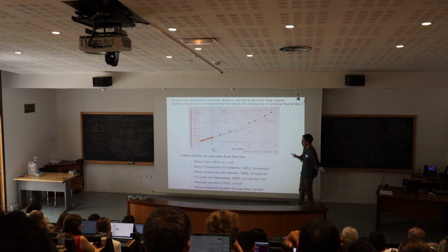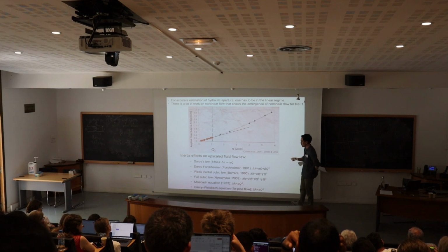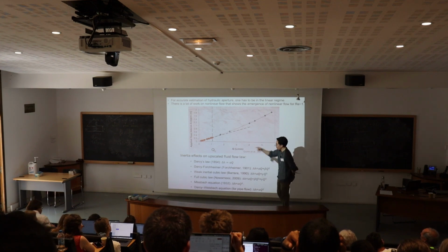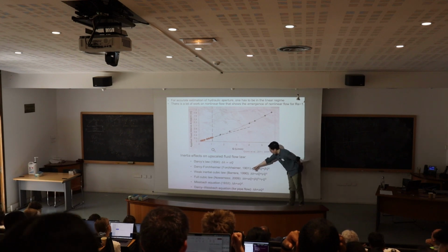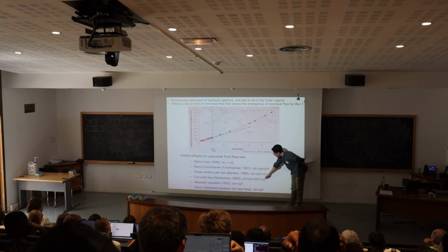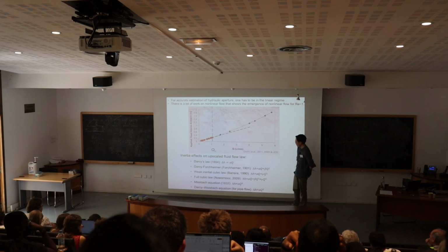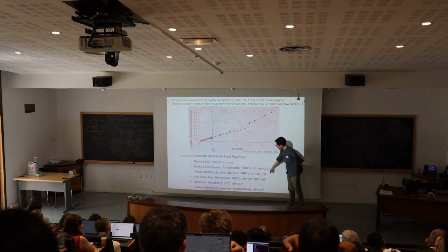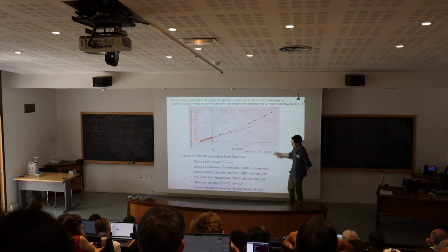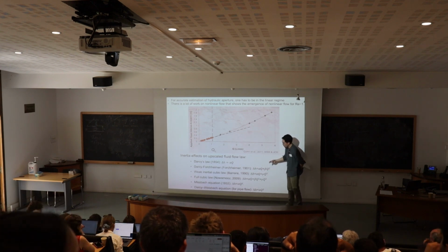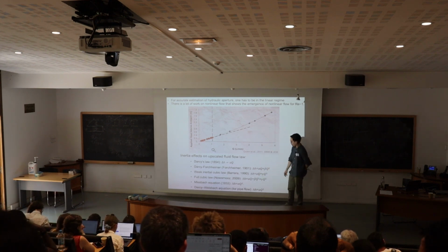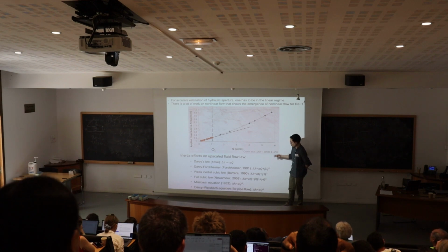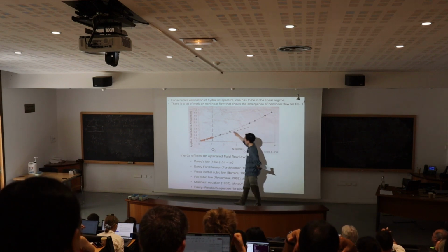And what's interesting is there's another cubic law. So you have to be careful when fracture hydrogeologists say cubic law, it's mostly the other cubic law that we derived. But actually there's another cubic law which is relating again the head gradient to the Q. And it's called cubic law because there is a third order term here. Okay? And I don't want to get into detail again, but some people argue that in the weak inertia regime where the flow is not turbulent, it has to be power of 3. Some people theoretically show that. And some people say we need both second order and third order terms, basically more fitting parameters. But depending on your problem, you can choose your model, and then you can nicely fit your curve.